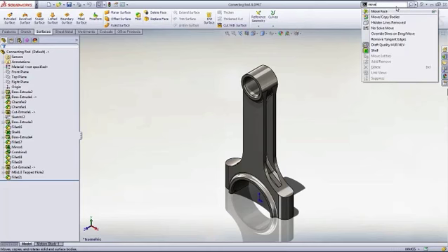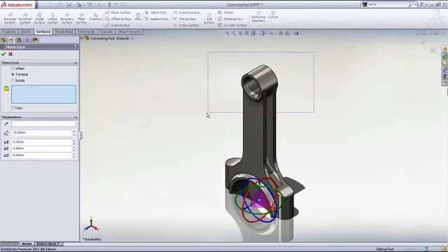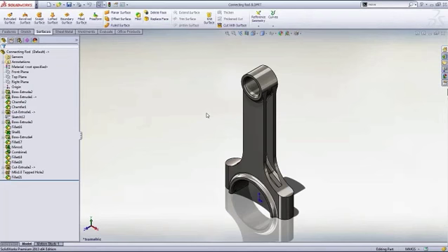All we need to do is select commands from the drop-down list, then just start typing the name of the command we're looking for. In this case, as I type Move, SOLIDWORKS presents me with a list of commands that contain that keyword. Once I see what I'm looking for, I can select it right out of the list and start using it immediately. This is a really convenient way to not only find tools, but access those tools you intentionally leave off your toolbars to save space.